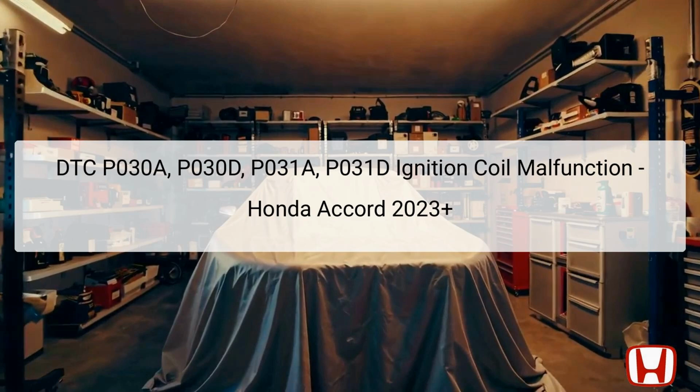The Powertrain Control Module, PCM, which is the brain of the vehicle's engine management system, detects abnormalities in the ignition signal and triggers the DTCs if there's insufficient change in the return signal from the ignition coil during triggering. Each code corresponds to a specific ignition coil responsible for firing that particular cylinder. Proper diagnosis and troubleshooting of these codes are essential to restore engine performance and reliability.